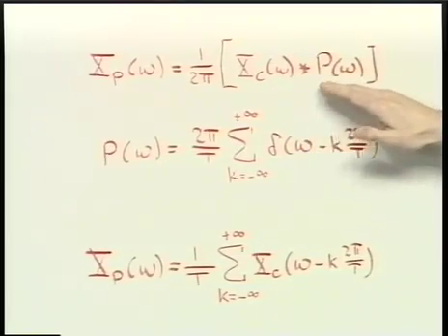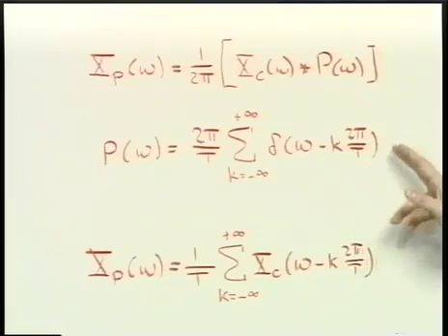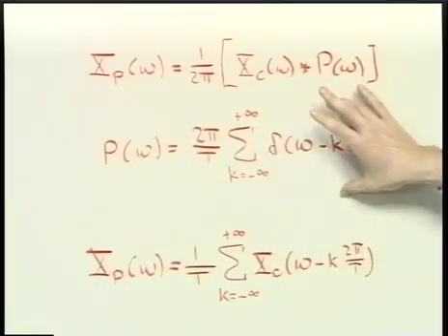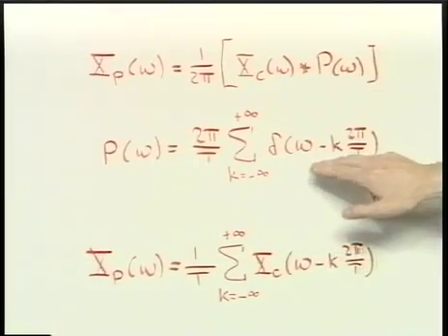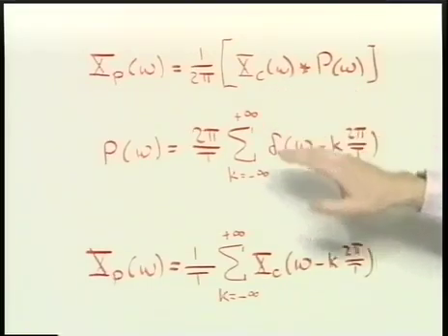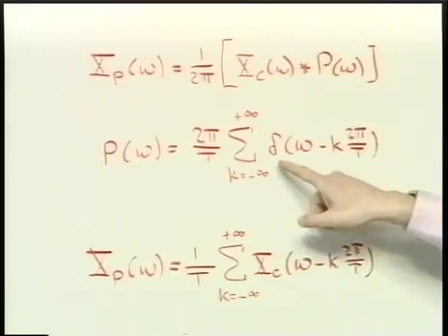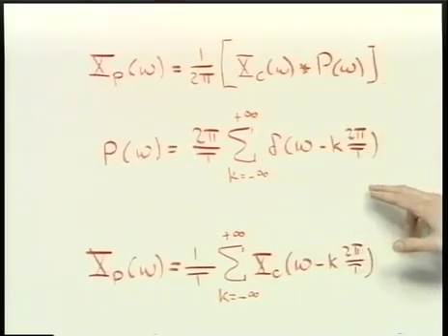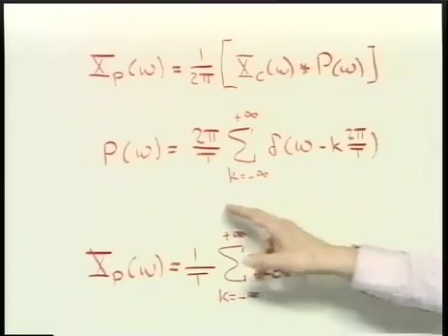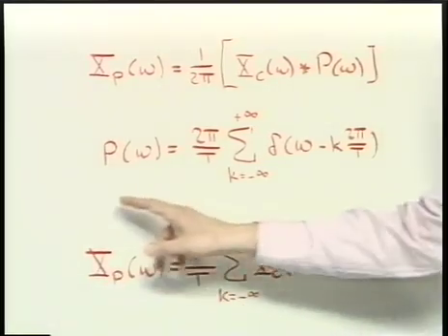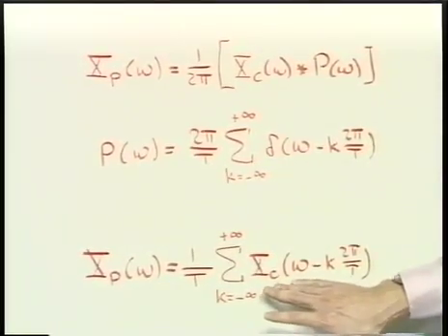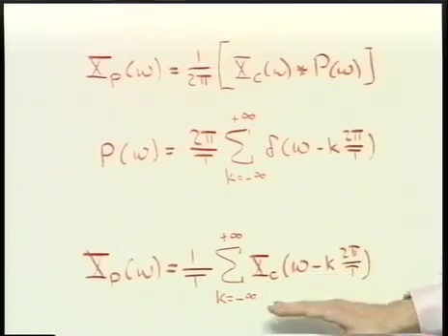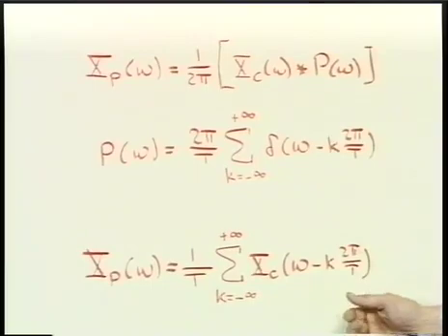Since the sampling signal is a periodic impulse train, its Fourier transform is an impulse train, and consequently carrying out this convolution in effect says that this Fourier transform simply gets replicated at each of the locations of these impulses, and finally what we end up with then is a Fourier transform after the sampling process, which is the original Fourier transform of the continuous signal, but added to itself, shifted by integer multiples of the sampling frequency.